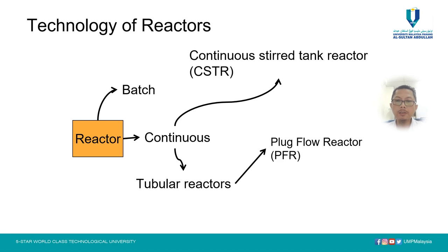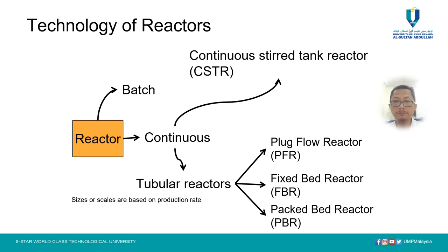Under the tubular reactor, there will be a blank tube, which is called plug flow reactor, or in short, PFR. And it can also have a catalyst inside, so we call it fixed bed reactor or packed bed reactor.